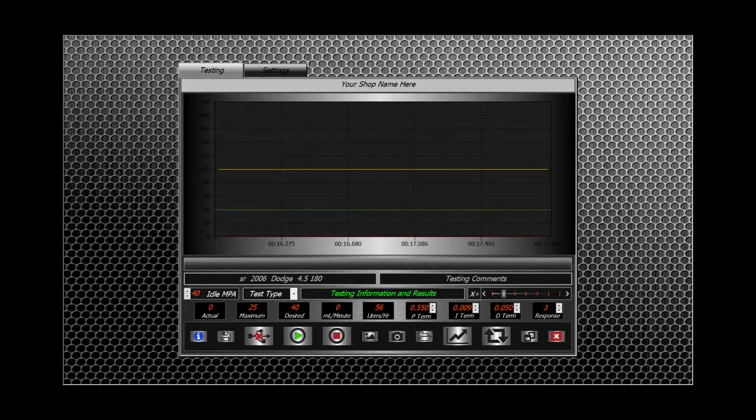What we're looking for here is the minimum deviation between our initial flow test and the end of the test. It'll start the flow test, and for a certain amount of time, it'll be sampling what the flow meter is putting out. Once it gets all its samples, it'll initiate the test, and it's looking for the difference between the initial and the end of the test. This one passed. This one was 3 liters per hour in excess on the second test.